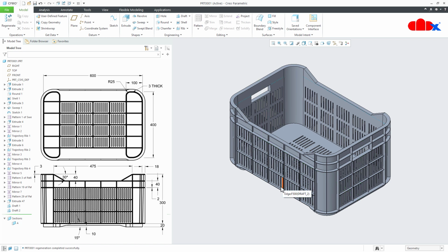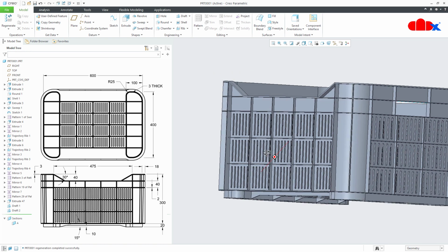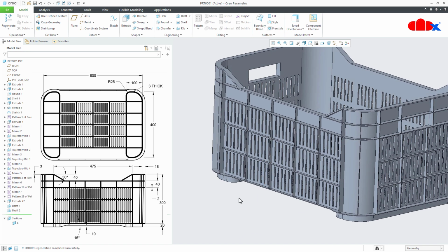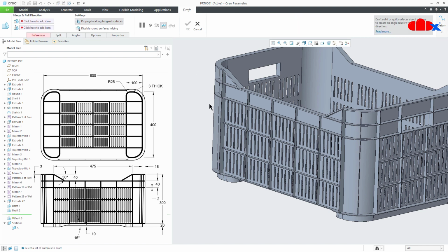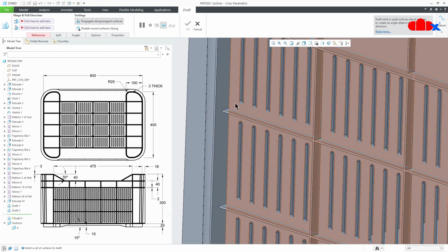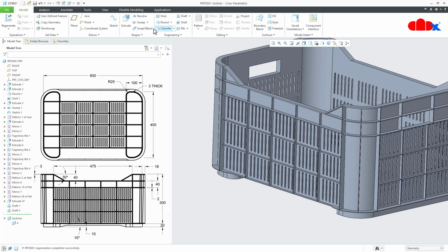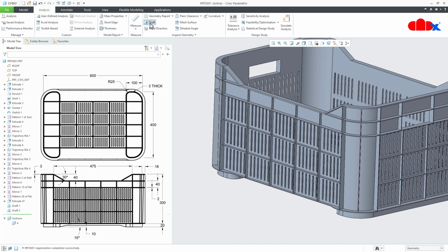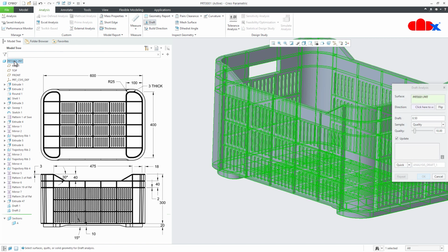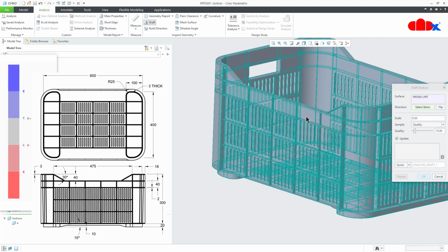Now if you see this surface, here the cavity will extract in this direction. So for all 4 directions, there is a split cavity. So that will move to the respective direction. So suppose you need to assign the draft to this face. Then you just go to draft. Now here this face will not stop. This is the stopping face. So if you go for the draft check, you can clearly see. Just select the entire part, and for the direction, you select this face.